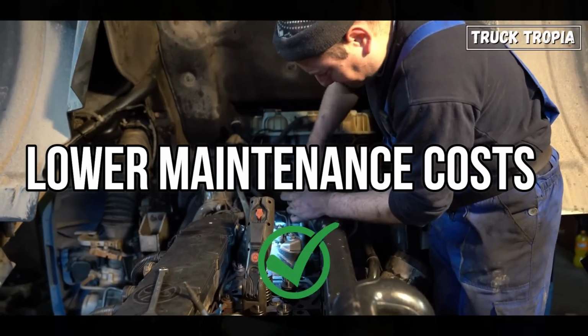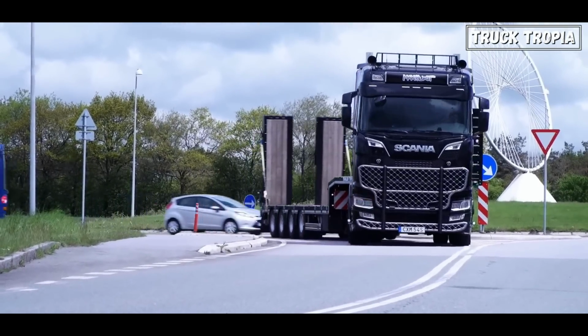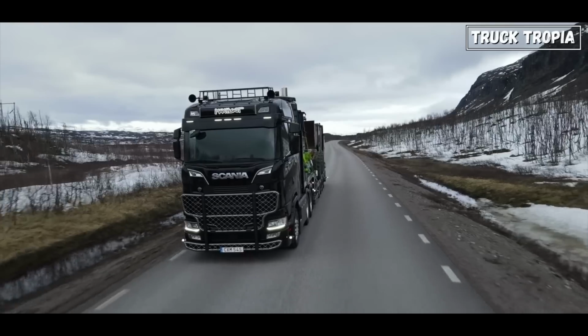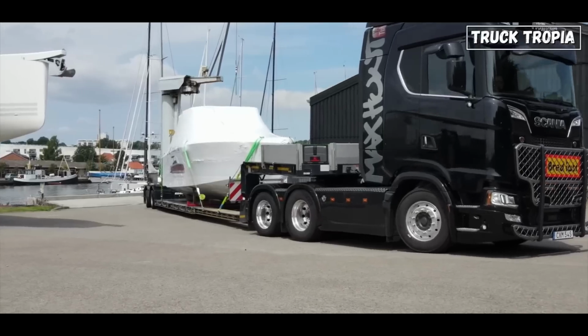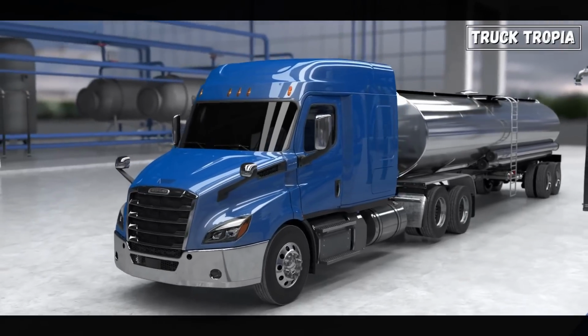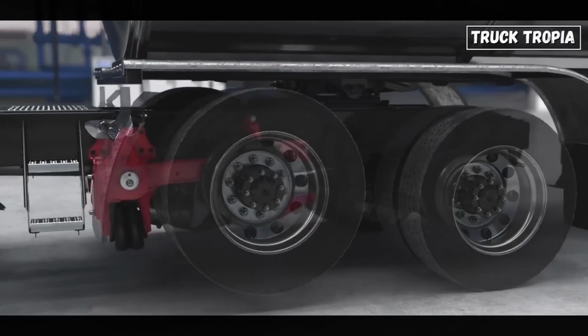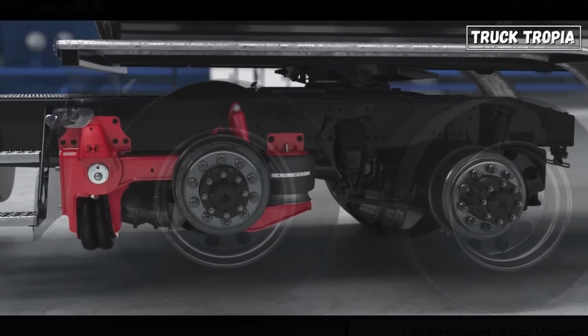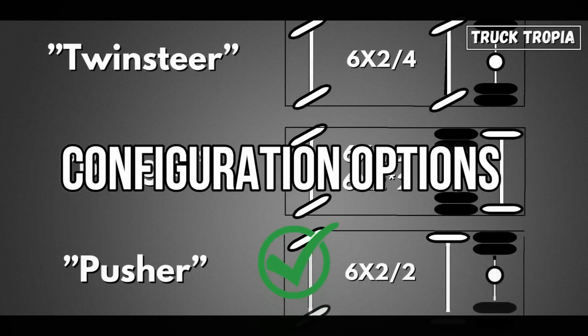Lower maintenance costs. The 6x2 configuration has fewer moving parts, making it less prone to wear and tear, and therefore requiring less maintenance and repair costs, as the tandem has 2 drive shafts. Also, it has fewer wheels touching the ground, as the 6x2 is able to lift an axle when not used, which minimizes tire wear.